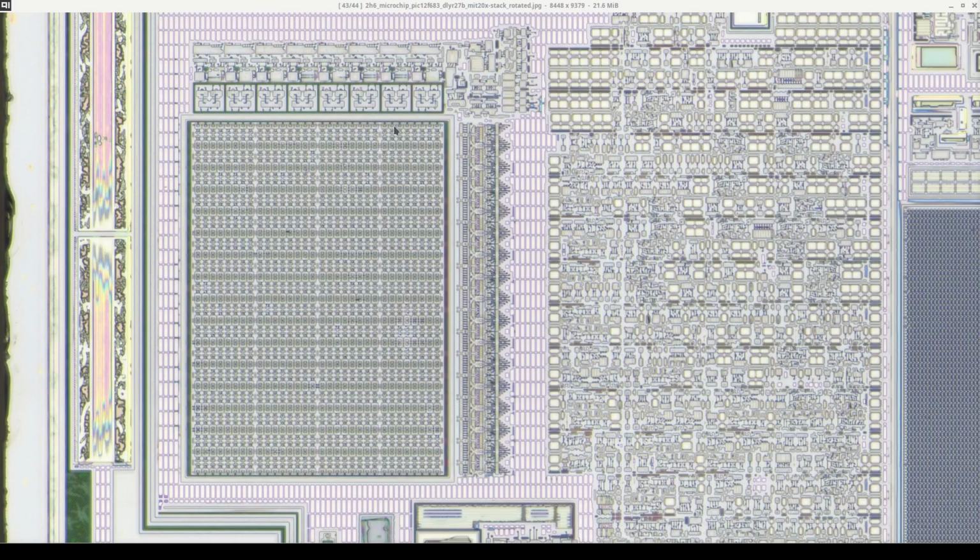We are currently looking at the substrate with poly and metal removed, and the actual bit cell array is clearly evident. However, the logical structure of the array from the datasheet is 128 bytes, and the actual physical array is obviously not 128 by 8. Just glancing at this, you can see there's more than 8 cells wide. This is, of course, for practical reasons.